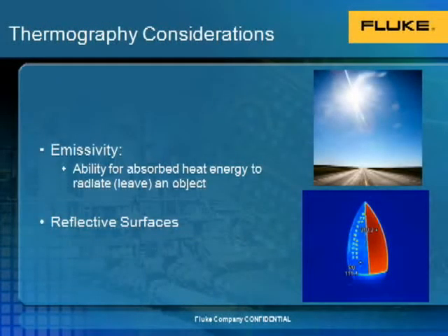One of the major considerations when utilizing thermography is emissivity. This is the ability for absorbed heat energy to radiate or leave an object. You can relate this to standing in the middle of an asphalt parking lot on a hot summer day. The reason it feels so hot is because the black asphalt is very good at emitting almost all of the energy it is getting from the sun. This relates to the reflectivity of certain materials as well.